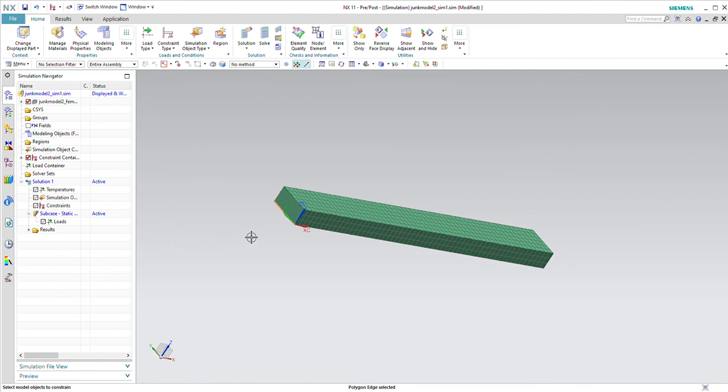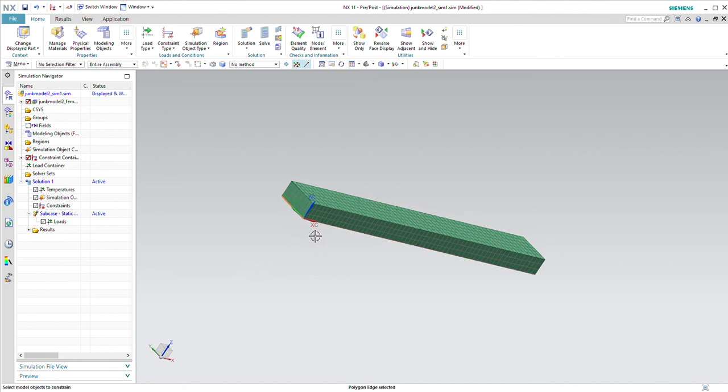If it's a pin attached right where that line is, the orange line, then that pin will allow rotation about the y-axis, but it will not let it go in the z direction or in the x direction. So x is degree of freedom 1, so I'm going to say fixed. Z is degree of freedom 2, I'm going to make that fixed. And actually, I'm going to go ahead and fix the y as well, just like it's a captured roller.